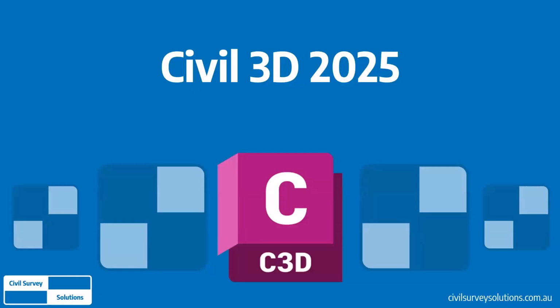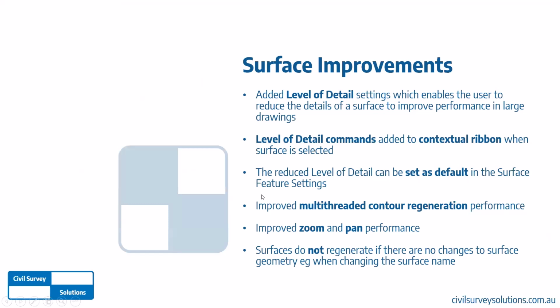And now we'll move on to Civil 3D. So there have been a number of improvements for surfaces, including the level of detail setting, which can now be applied to an entire drawing or individual surfaces. You can also set the level of detail as a default in the surface feature settings.